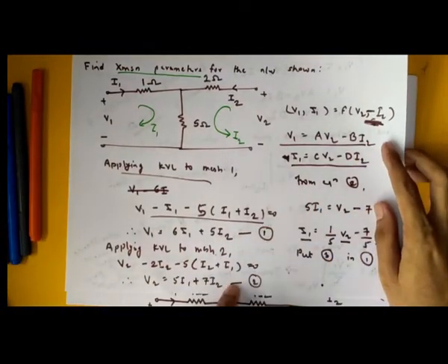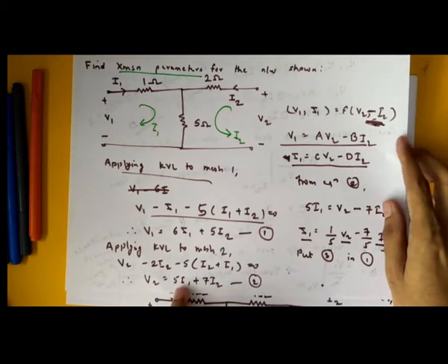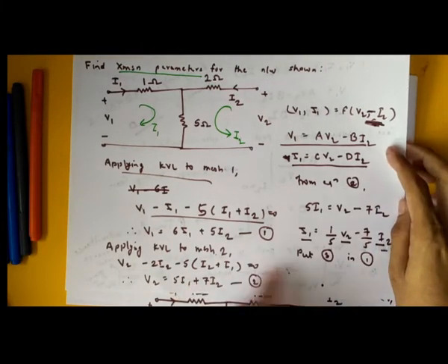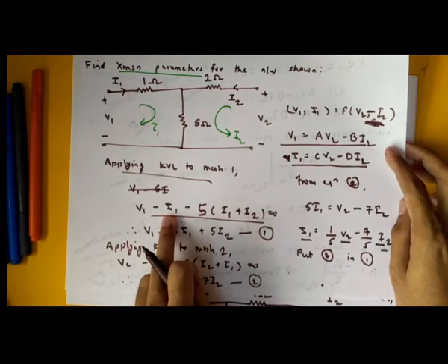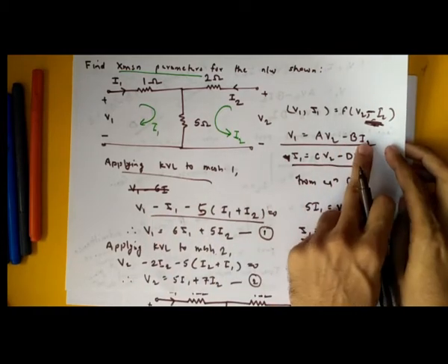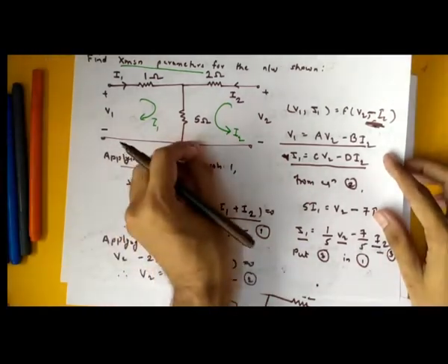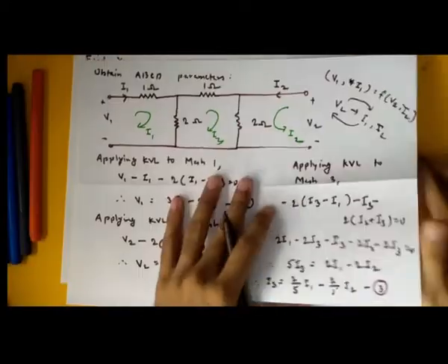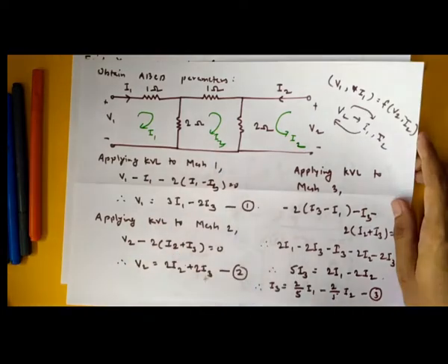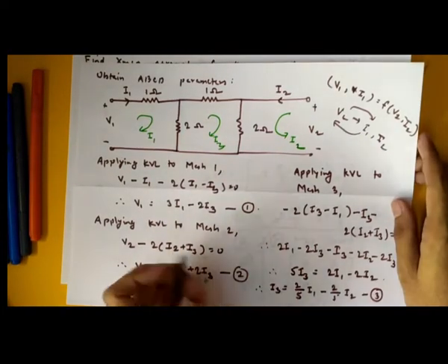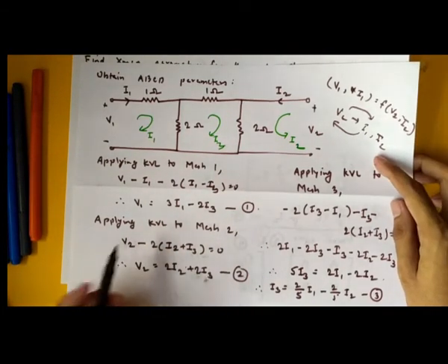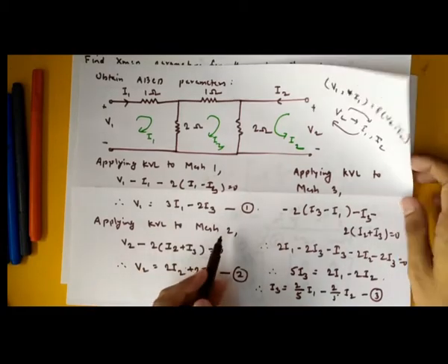We got equation 1, equation 2, right? We just took equation 2, found I1 and then substituted here. We got V1 in terms of V2 comma minus I2, and automatically I1 also we got in terms of V2 comma minus I2. But when one loop was increased here, as shown here, how many times do we have to do substitutions? You apply KVL 2 times, 3 times, sorry. Then what do you do?